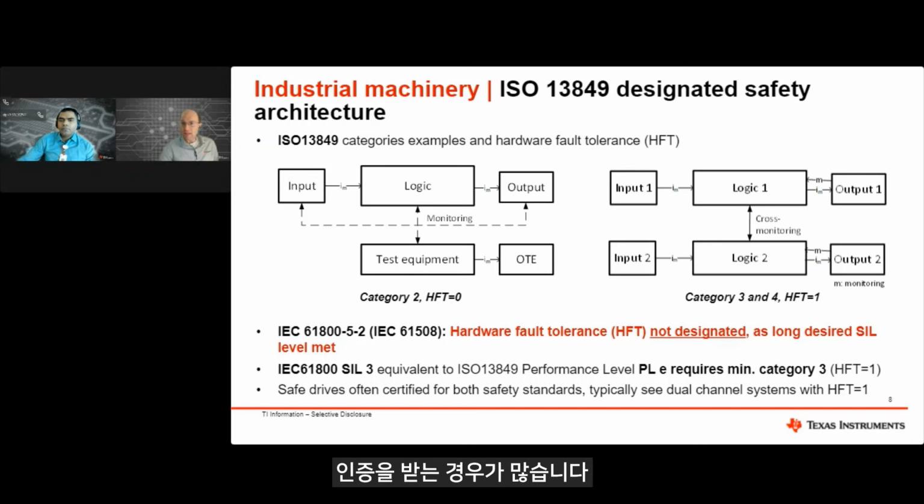The blue tabs allow the user to enter custom values as per the end application. The safety function includes the FIT estimation tab, the product function tailoring tab, the safety mechanism tailoring tab, pin level tailoring, and finally the custom diagnostics. The green color tabs, which give users access to the results, are classified mainly as summary and detailed. The Results tab shows the results for both standards, ISO 26262 and IEC 61508. The underlying data used in producing both results is coherent, and the computation done is as required for the respective standards. We will see some more examples of the customization allowed in the blue tabs in the next slide.